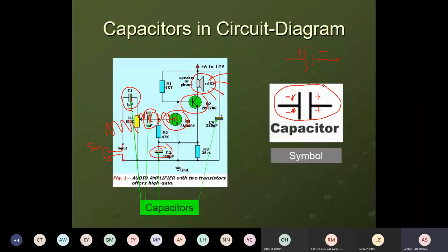Okay, but the loudspeaker will have its own power supply. There is a power supply here for the loudspeaker. The power supply used by the loudspeaker normally is a direct current, direct voltage. So we don't want that direct current to pass through this capacitor and reach the microphone. Here the capacitor works as a safety. It allows the alternating current from the microphone to pass through to the amplifier to be amplified, and blocks the direct current from the loudspeaker from reaching the microphone.